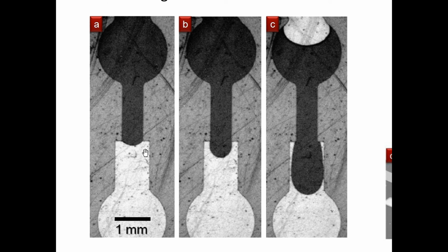If you're trying to push that balloon out of the channel, this balloon is going to actually push back with some amount of pressure. So this liquid, just on its own, actually pushes back with some amount of pressure. And that is what they're calling a valve. The reason they call it a valve is because normally it'll basically block the fluid flow, but if you put enough pressure on it, the valve will actually break, and then you'll get the fluid flow through there.